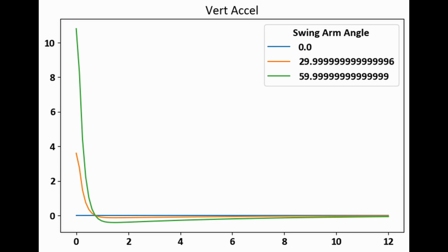It starts high, and then vertical acceleration is still positive, but it starts to decrease. And when it gets to the top of travel, it then dips below zero, which is when we get less normal load on the tire, and then it comes back up and settles at its static value.